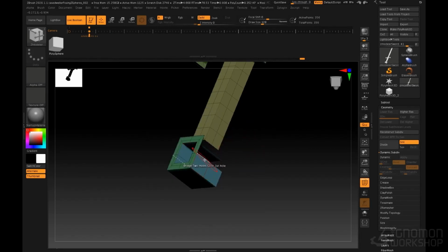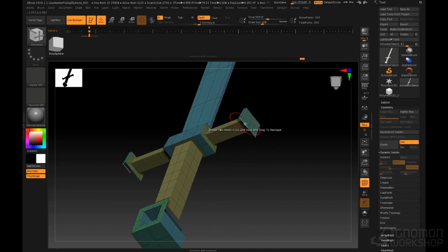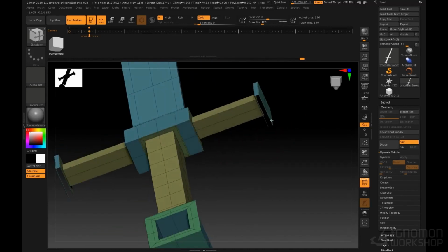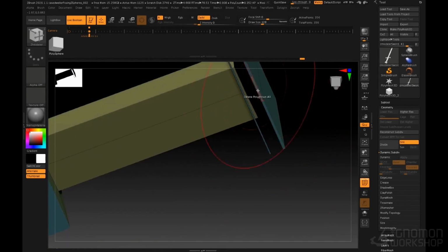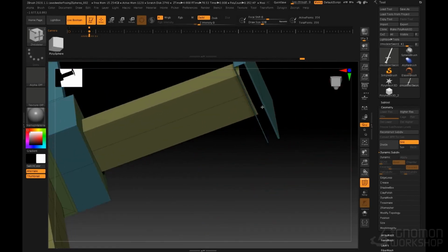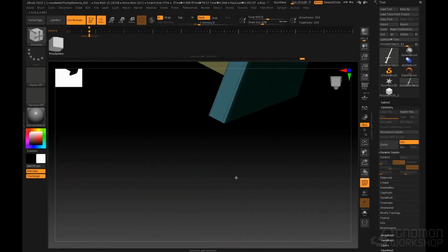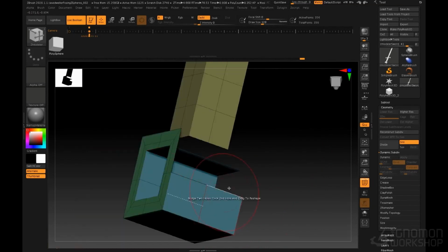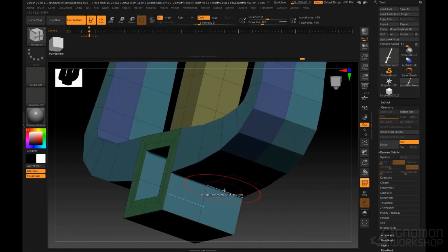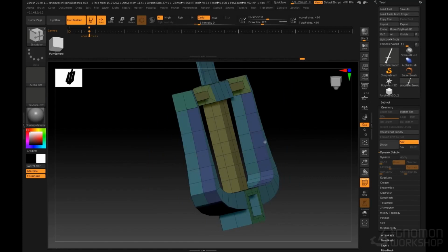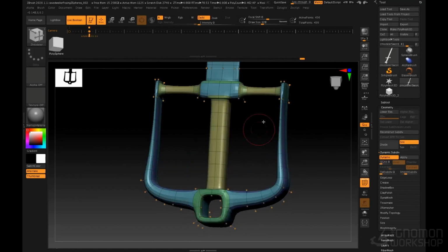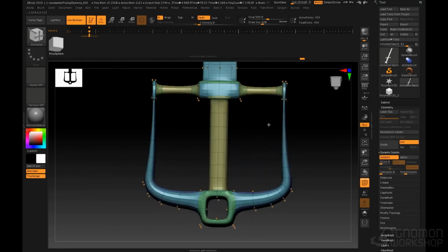We're going to go ahead and click the first edge. The first hole, we click an edge, and then we're going to zoom in and we'll click an edge here. Now we need to be careful because it's a very small hole there, so you need to make sure that we actually get the edge on the hole. So let's go ahead and select that. And that's our first hole, and now we'll rotate around, come back down to the larger hole, and then click that edge. That's our second hole, and now it bridges those 2 spaces. And it creates this really nice kind of hand guard.